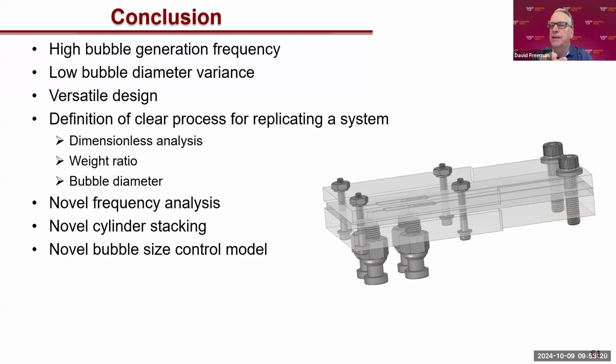In terms of bubble size, I'm looking back at some of the earlier material. You were trying to hit a target, and your bubble sizes were a bit larger than your target. Is that correct? Yes, sir. We were not able to create a combination of airflow rate and liquid flow rate that would result in a bubble that small. It would result in a bubbly flow regime, and this microfluidic injector doesn't work very well with bubbly flow regimes. It relies on slug flow.